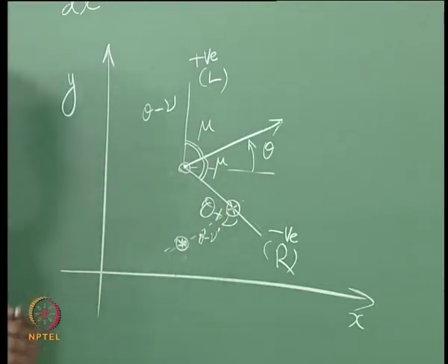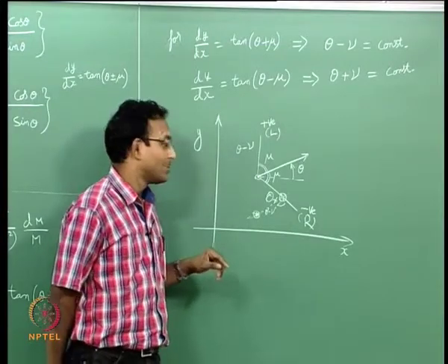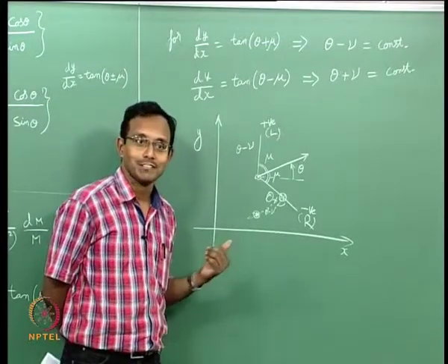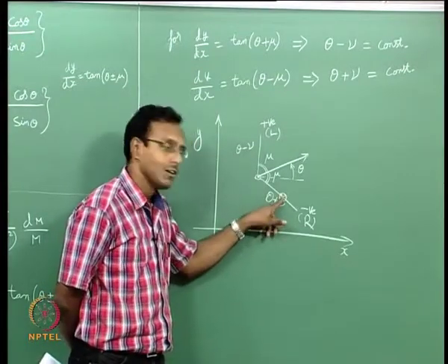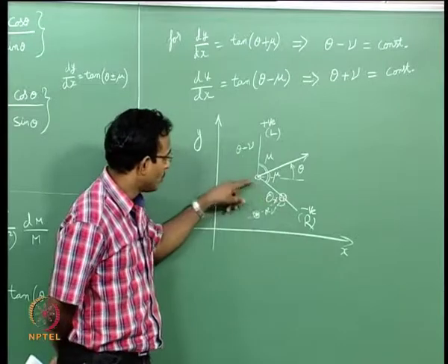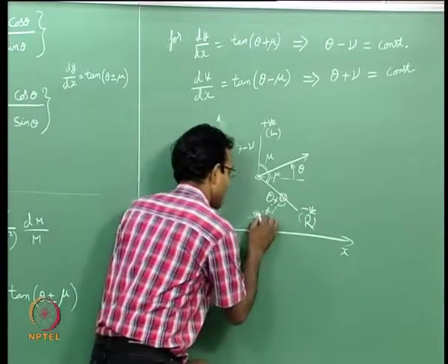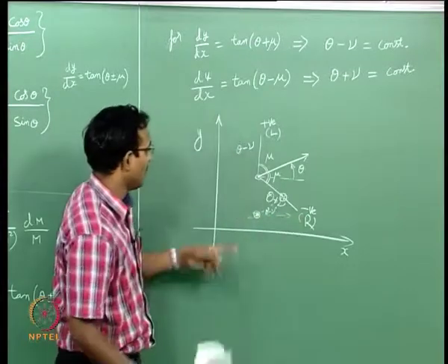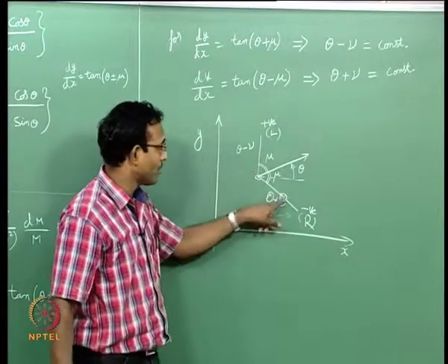Now we will go back and look at our previous statement which we were waiting for, which is we said supersonic flow depends only on the upstream conditions. Have I used that here? Yes. This point was found from two upstream points. How do I know it is upstream points? We already assumed the velocity vectors to be like this. One velocity vector like this, one velocity vector like this. Based on these 2 points, I got this point.